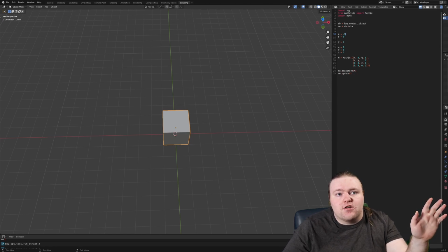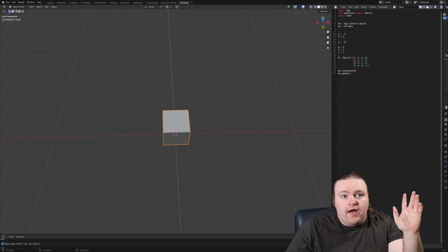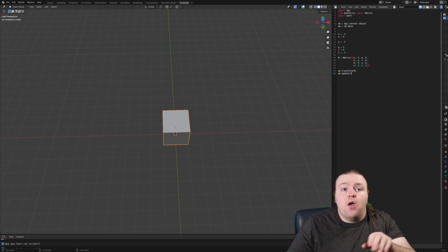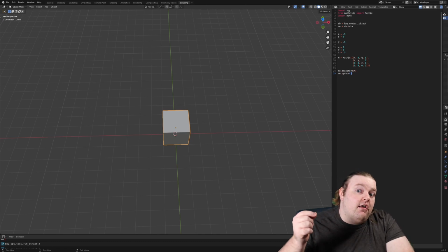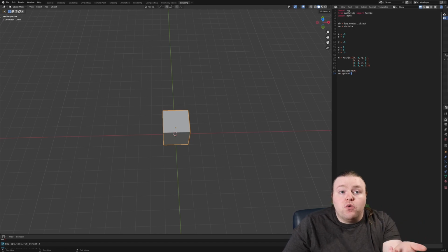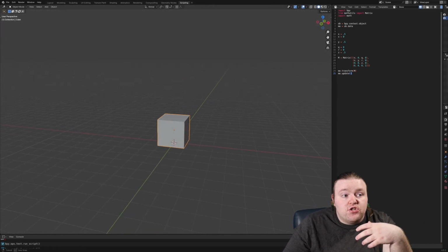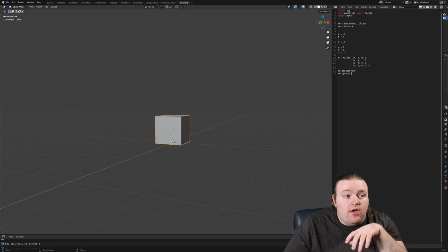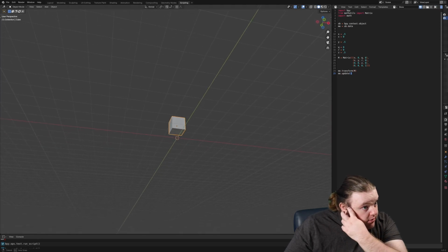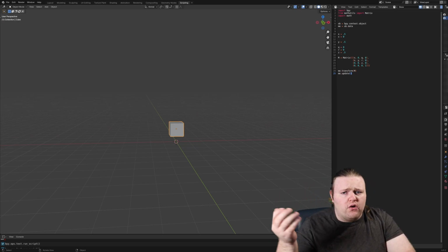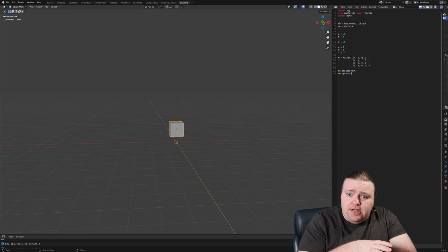So we're going to say x is actually 0.5 and y is 0.5 and z is 0.5. This is an unskewed printer from our math here. There's no skew, but the printer is printing everything at half scale. I want you to just think about why that is if you're unfamiliar, but we're actually going to be multiplying by 0.5 on all of the positions, the lengths of all the vectors unilaterally. So we're going to end with a cube that is half size. Well, that's a problem. We don't want that. I mean, this is a problem that's not realistic, right? Something else is way wrong with your printer. But if that was happening, you don't have to necessarily fix the printer, right?